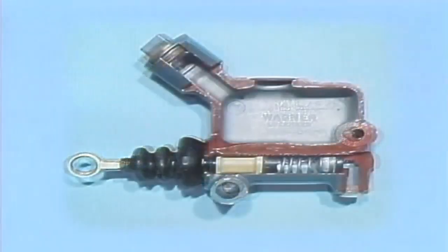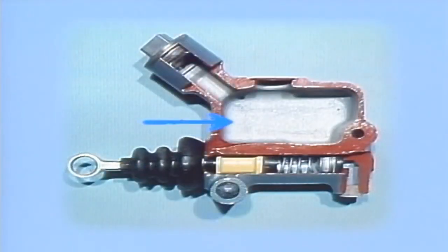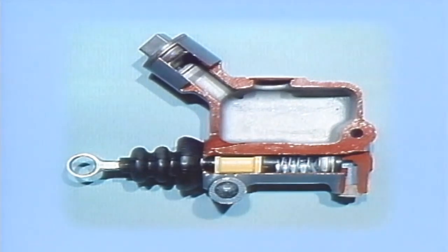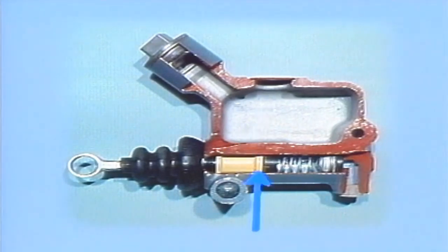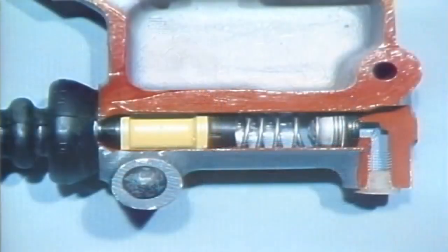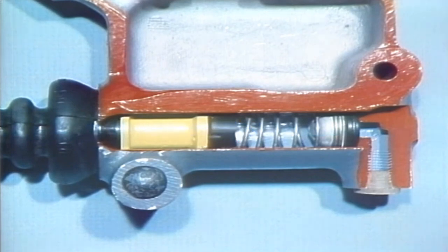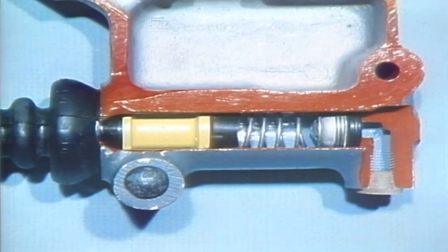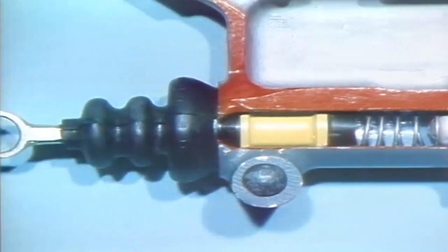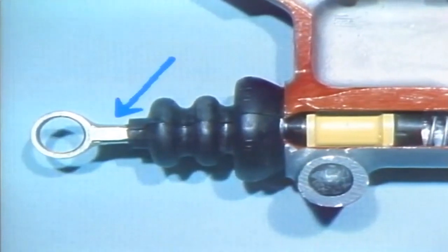The master cylinder has two basic sections. One is a storage area, called a reservoir, for the fluid. The other section is a cylinder, which contains a spool-shaped piston. Small holes are drilled through one rim of this piston. The cylinder also contains two sealing cups, a return spring, and an outlet check valve, called a residual pressure valve, with its own spring. A push rod transfers brake pedal action to the piston.